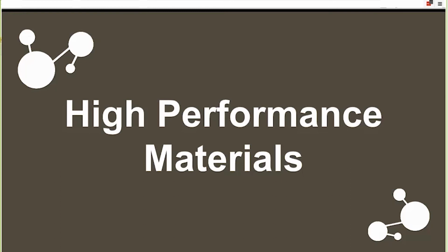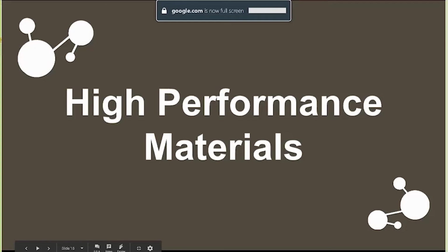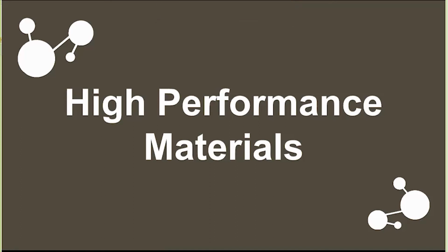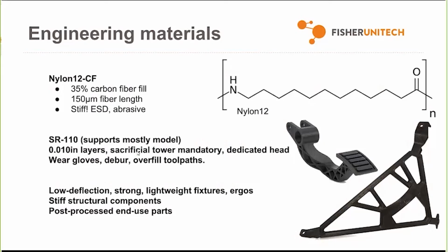Okay, when you have an application with very specific needs, that's when you're reaching for high performance materials. Now, most of these are high heat materials, and so that means that they might require a mechanical upgrade to your machine, depending on how you bought it, to allow the chamber, frankly, to get hot enough, and in some cases to allow the components to last. I'm going to try and get through this pretty quickly so I can get to questions.